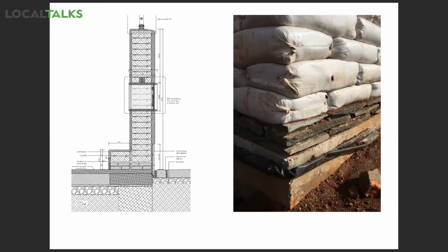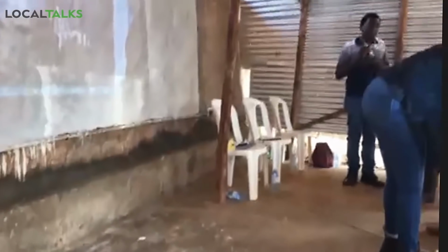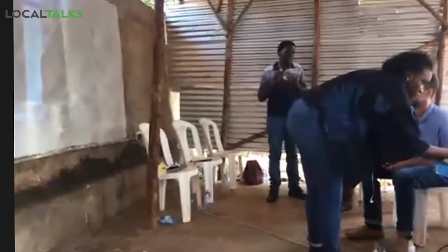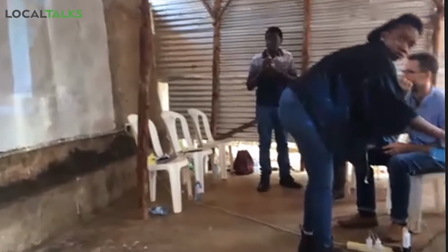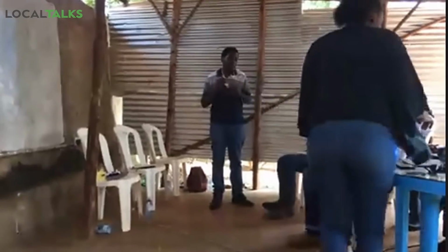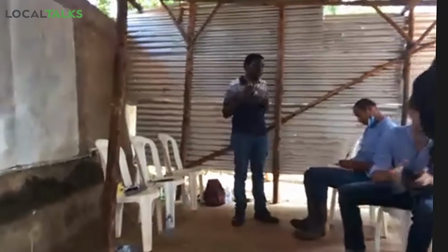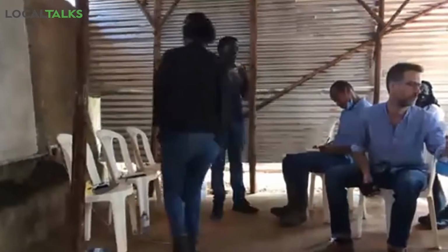Maybe you also mention the timber aspect. For the other exposed things, like the timber, we are using timber chippings within the plaster. There we are adding some borax, and the timber we are also treating with borax. But even if you treat with borax and there's moisture getting in, it will still dissolve the borax, and later it will be eaten anyway. So moisture is very important. Keep it dry.